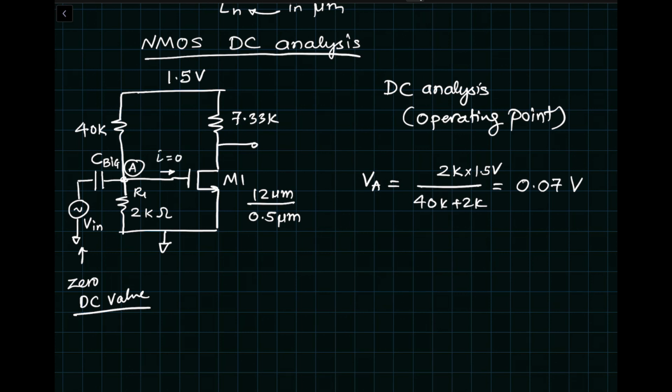So this makes our life a lot easier when we compare it with the bipolar transistor. In the bipolar case, there is base current flowing, so to deal with the base current, what we had to do was we had to do Thevenin's equivalent of the circuit looking over here. In this case also we could do the Thevenin's equivalent, but the value of the Thevenin voltage would come out to be this. There will be a Thevenin resistance.